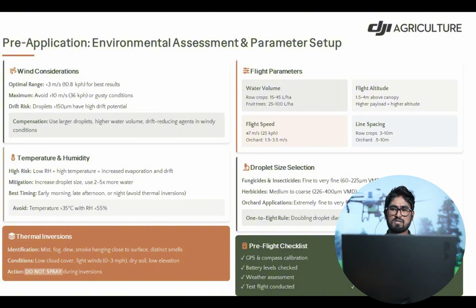And also we must identify some buffer zones in the application area. If you have WS paper, meaning water-sensitive paper, or OS paper, oil-sensitive paper, we can use those papers to monitor the field application efficiency of our drones, and monitor the droplet size and how many droplets can be observed in the unit area.